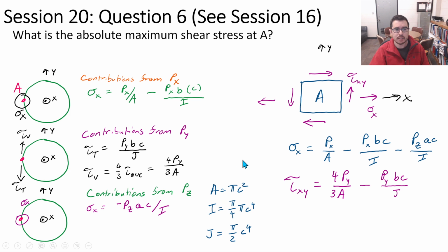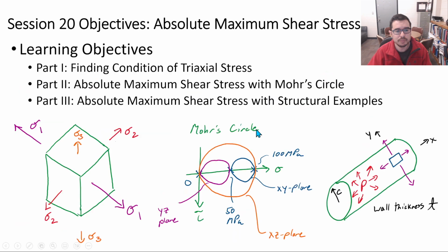These calculations, and then putting the normal stresses together and the shear stresses together, are what you see here. So if we were to plug in numbers for this expression, we should be able to figure out sigma x and tau xy, and then look at calculating a condition of principal stresses where we have one of the principal stresses being the largest possible.